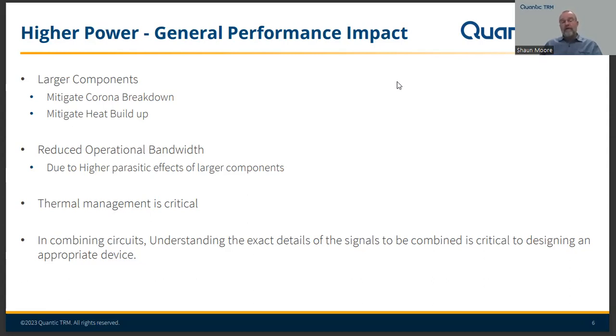An example of that is a low power ferrite based power divider. We routinely build those power dividers with 100-to-1 bandwidth. That's just how much bandwidth you get out of them without really struggling very hard. We routinely get 100-to-1 bandwidth out of our small low power devices. Once you go up to say 100 watts or so, if you get a 10-to-1 bandwidth out of it, you're doing good. And when you go even higher in frequency, the bandwidth continues to drop.